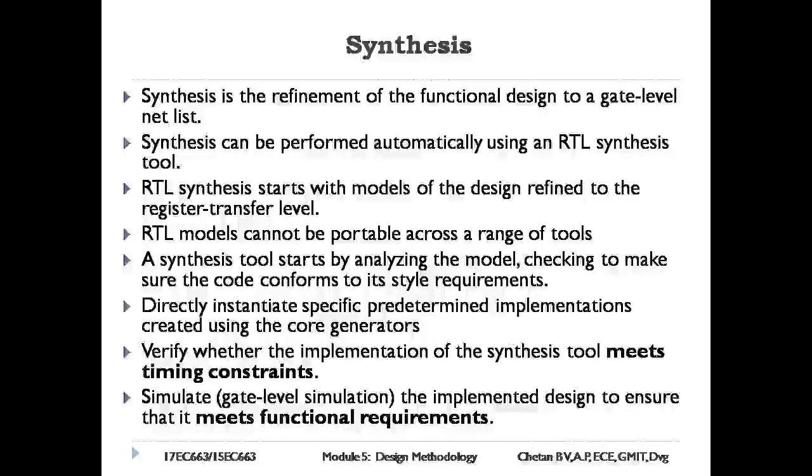Synthesis. Synthesis is the refinement of functional design to a gate-level netlist. Synthesis can be performed automatically using an RTL synthesis tool. Automatic RTL synthesis is used for FPGA-based designs. Custom design is required if a design is complex, has very high performance requirements, and is implemented as an ASIC.